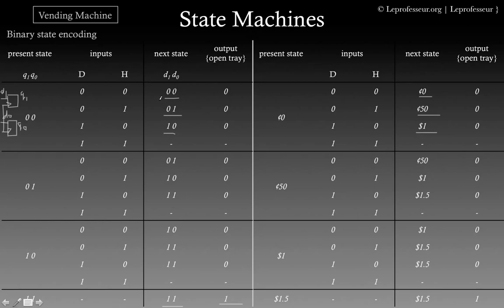But if your state machine is being used in FIFOs, or producing some logic which is being used in different clocks, or this machine is making use of inputs coming from different clock domains, you might have to reconsider your design.